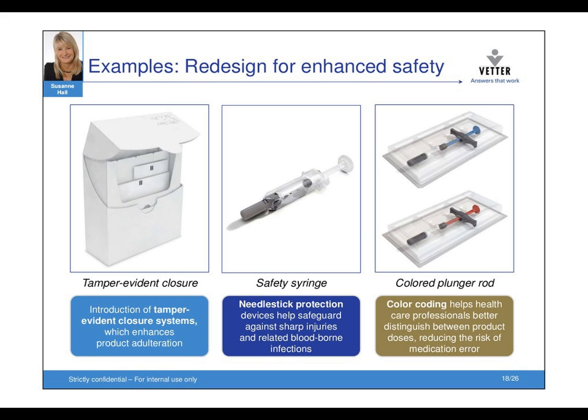As important as patient convenience are the safety aspects of the product. There are several options to meet the requirements of safety. First of all, the packaging should be protected against counterfeiting. Enclose the package with a tamper-evident label, or glue the box and open the perforation. The box is open and you can't close it again. If you don't want to glue the box, there are several options from the suppliers of folding cartons on the market, without any gluing, just with small adaptations on the line.